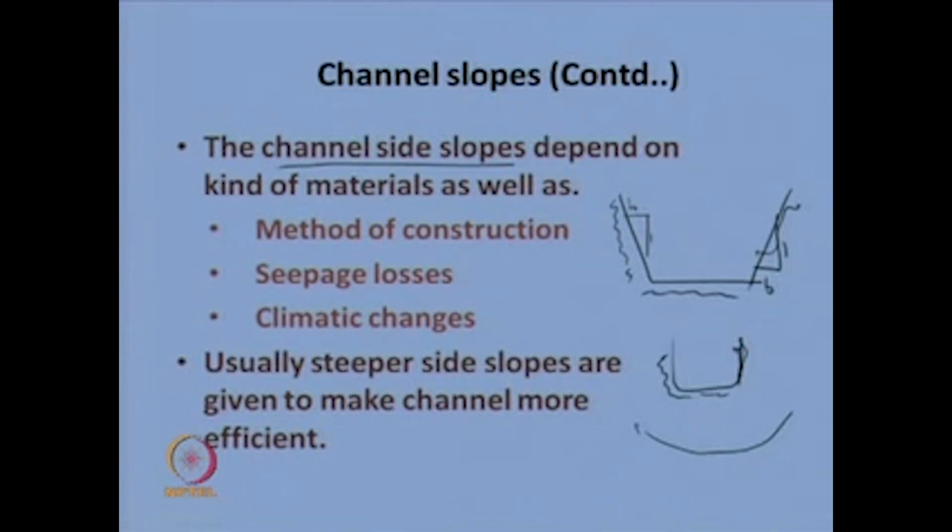Also based on the method of construction, you have to design the channel side slope. You also need to see whether you have to minimize the seepage losses or whether you are allowing certain seepage losses, so that the general area in the region is getting recharged. Also you need to see the climatic changes. All these factors depend on determining the channel side slope.